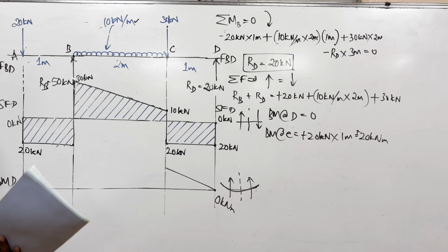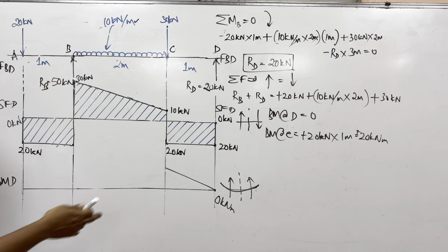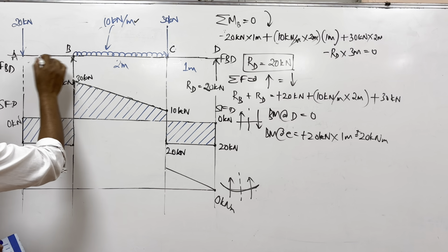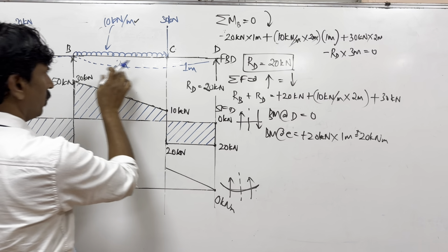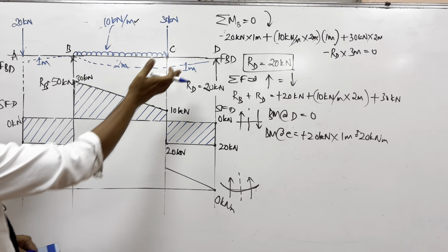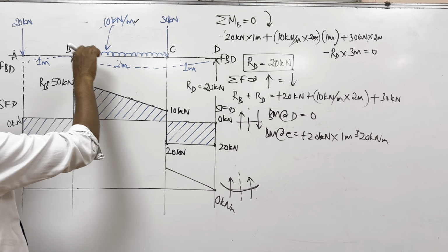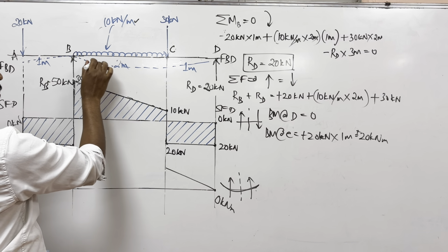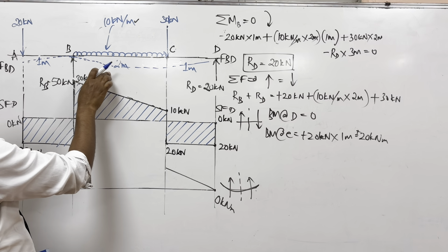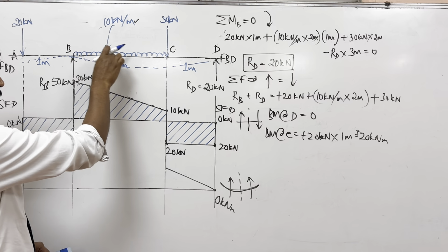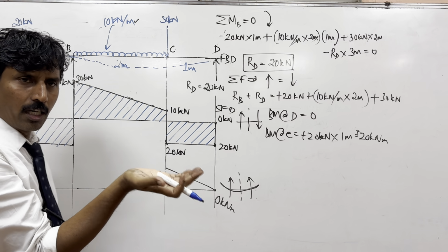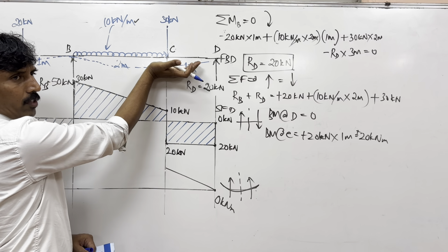In this beam, you can almost predict by common sense, everybody knows. You may not know the engineering convention, but you know that this beam is going to bend like this. Again, this beam is going to bend like this. From here to here, it is throughout sagging. Only from here it can actually start hogging. Sagging means not just below the line; see the curvature of the beam.